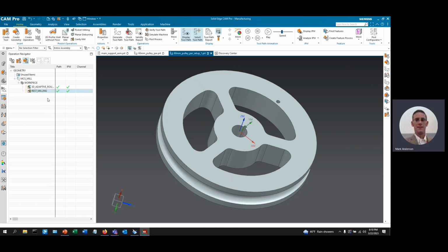You wouldn't be able to do contoured rotations as far as tool in motion like surface machining, but you would be able to position 2 axis in a position and then do a drill or a 2.5 axis mill. So you are capable on those types of machines. The post processor handles that, not the software. When you get into axis in motion while cutting, that's when you have to have full 5-axis software, which is an upgrade.